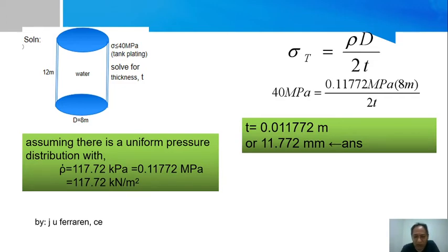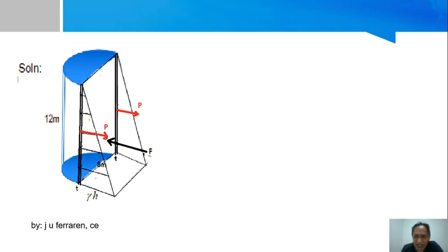Now, if I'm going to solve the thickness using the longitudinal stress, actually, you can even consider half of this as the thickness. But since we say that our tangential stress is critical, then I can use this as my governing thickness to make it safe for both longitudinal and the tangential. Maybe, this is already the answer. But if you have knowledge in dealing with hydrostatic pressure, no?